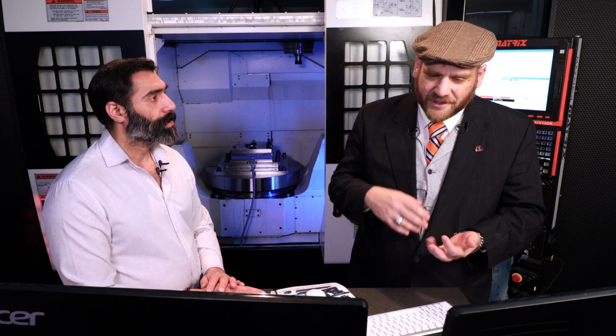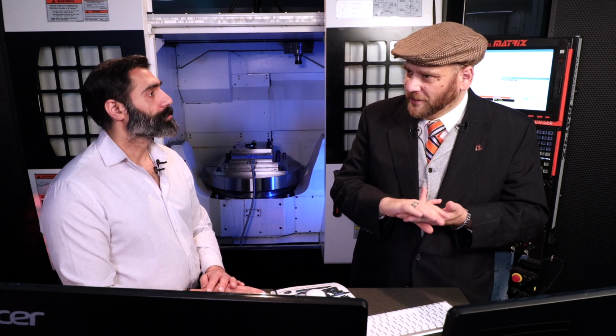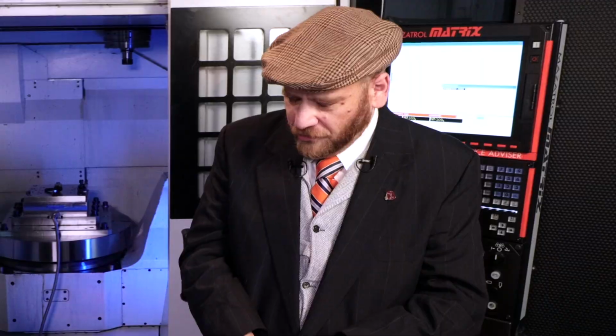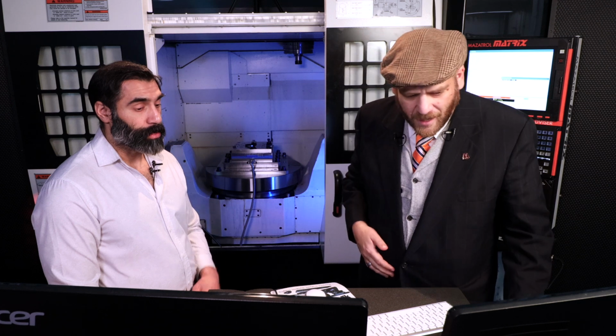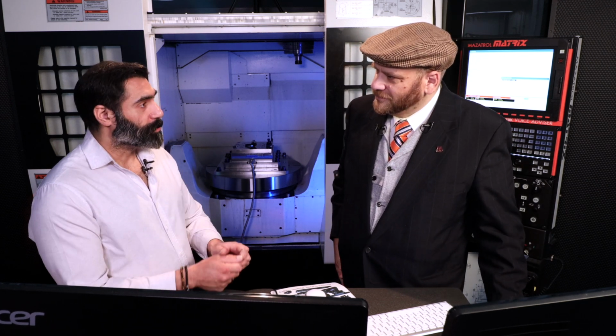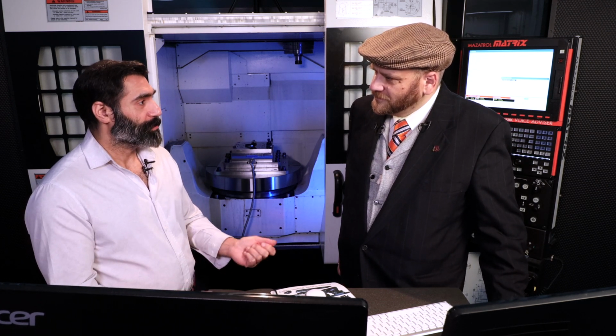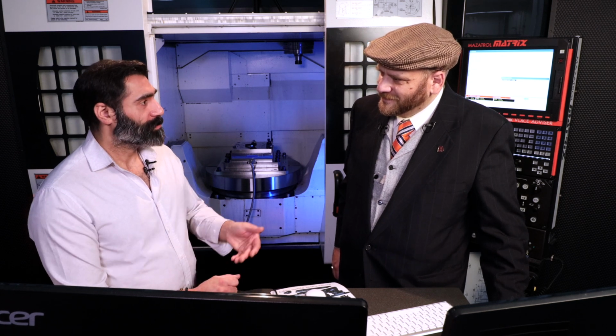I can define a tool to say this is a tool we peck drill with, this is a tool that we do a standard tool cycle with, feed down, rapid out. I can tell it that it's a tap. If it's a tap, it's going to set the speeds and feeds into the rigid tapping automatically for me. Yeah, I can see that as being a huge time savings, because otherwise you'd be opening up your machining book and looking at the speeds and feeds to use.